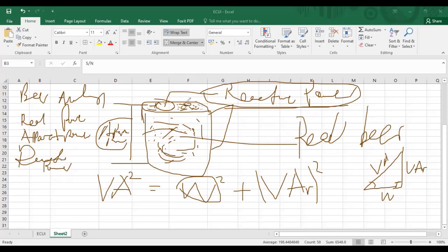Like in electric motors or in some other devices, it helps to create the magnetic flux to allow the drive for motion. So the reactive power is not so useless, so to say, but too much of it is not actually good. Too much of the reactive power is not good because it is used to overcome torque in most mechanical devices. So we need to understand that. Understanding this will help us. If you have too much reactive power in the system, your power factor will be low.